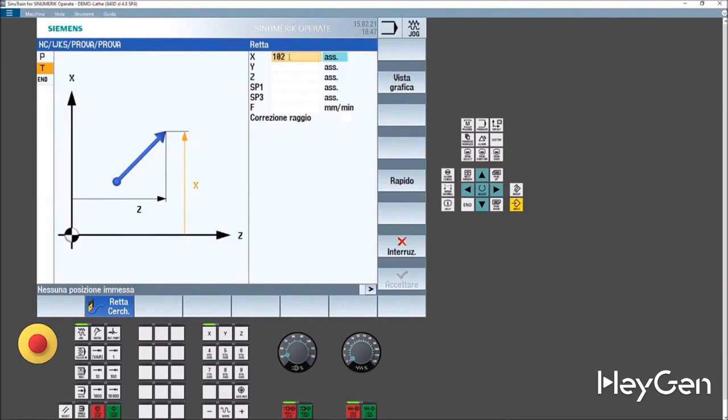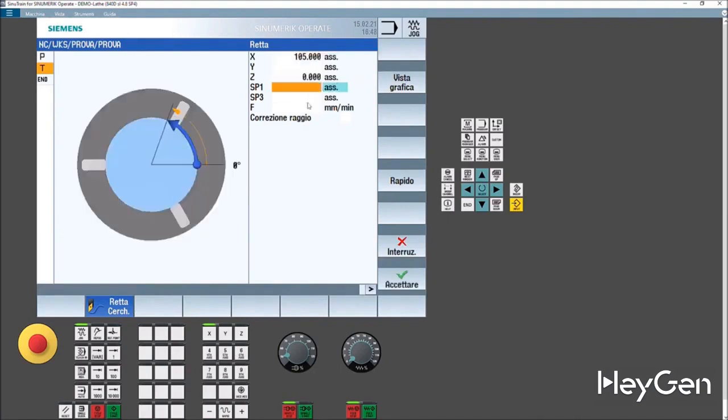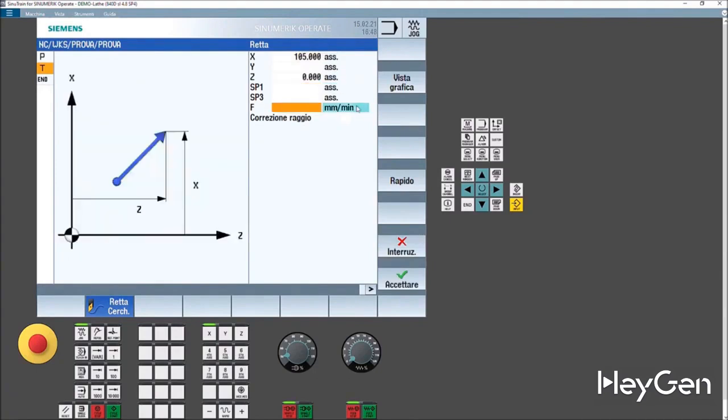Here I have a doubt. I think it stops at 107 because we set a safety limit, but I think it only applies to fixed cycles. So, just to be safe, it might go up to 110. Then you'll learn to know your machine because it also depends on the parameters, like X105, Z0, F0.3. Sorry, I'm getting closer to the piece. I'm approaching it quickly. Perfect. You see?